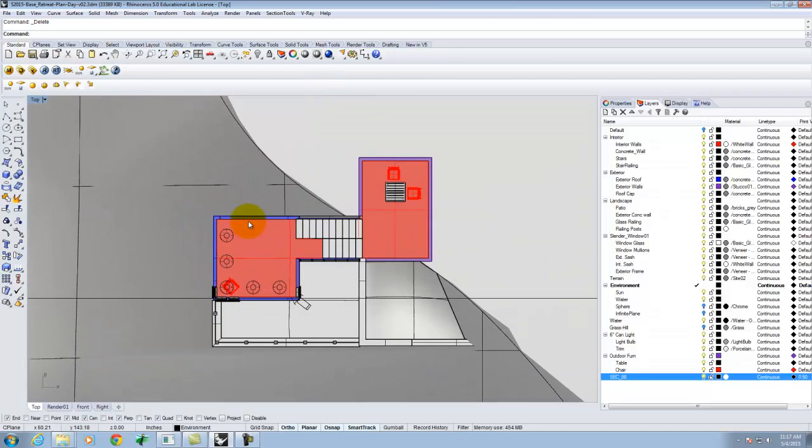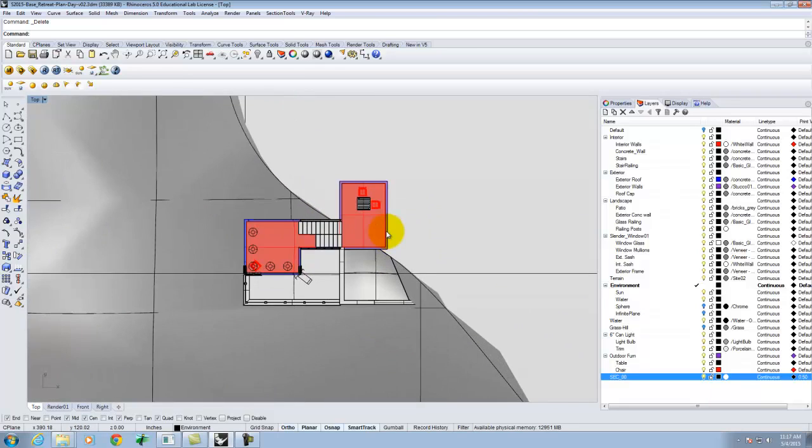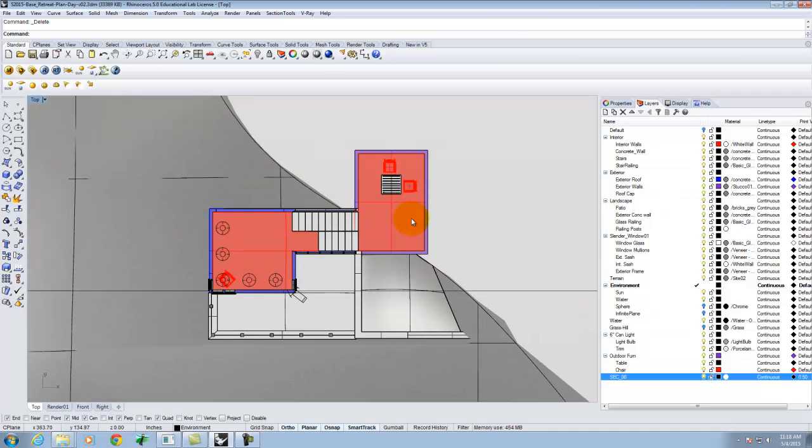And now that I have it set up, I want to set a named saved view that I can come back to. And I know I have the view top, but my zoom level, and ultimately when I do a few of the clay renderings and stuff, I'm going to want to be able to come back to this particular view. So I'll zoom in to the extent that I want to see this, right? So we'll pick something about like this.